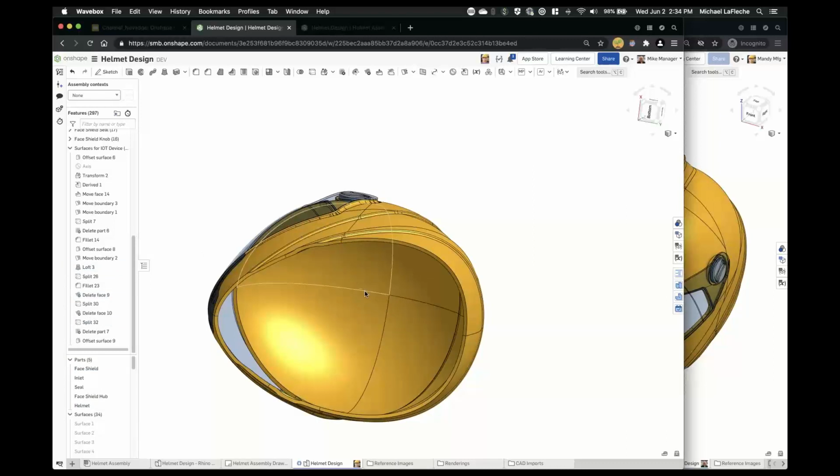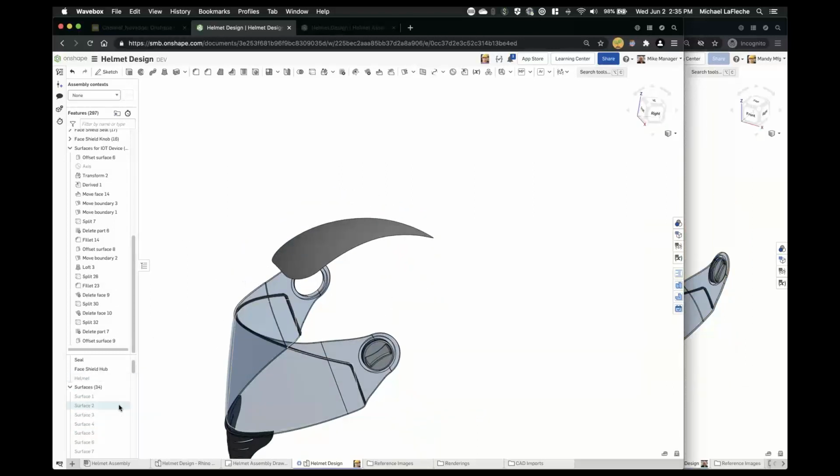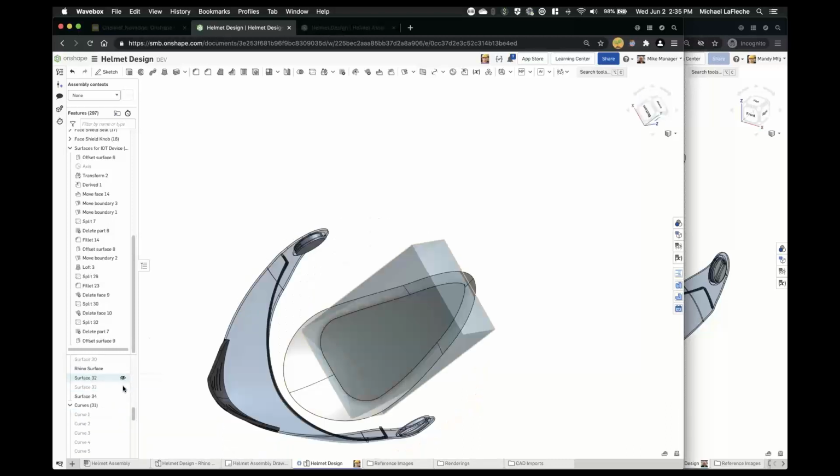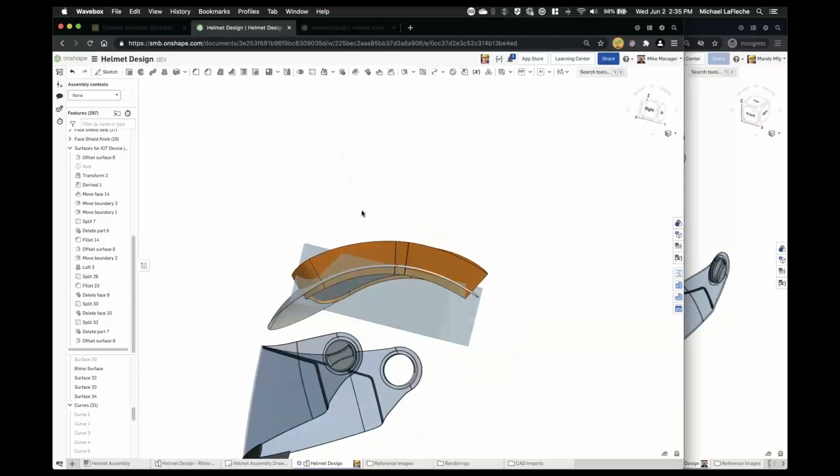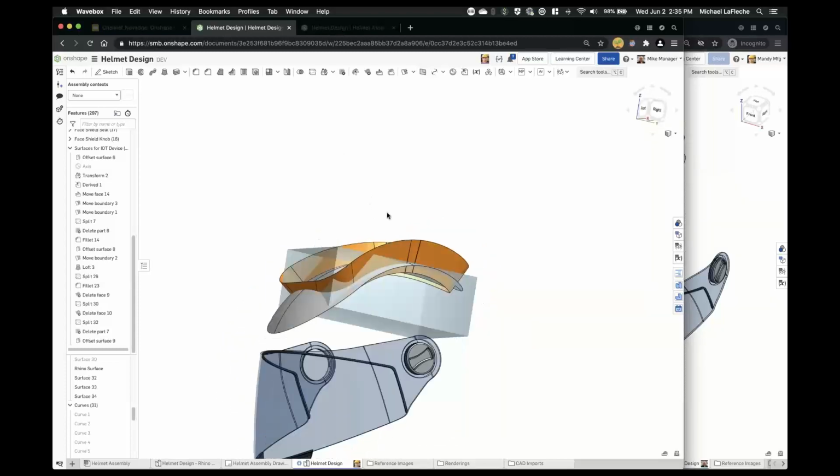live. So I have some surfaces right here that I've created from the Rhino surface. Right, so I can display just the surfaces. Here's the original Rhino surface. I did an offset inward. I had a couple of other helper surfaces that I used to create this geometry in here, right?